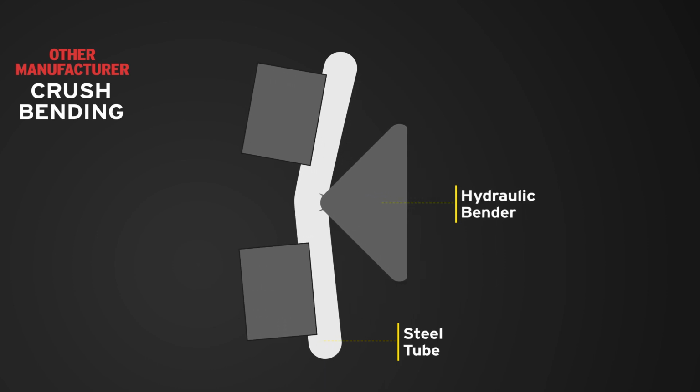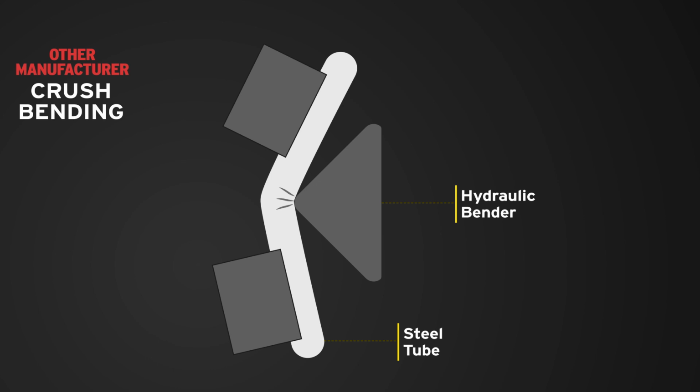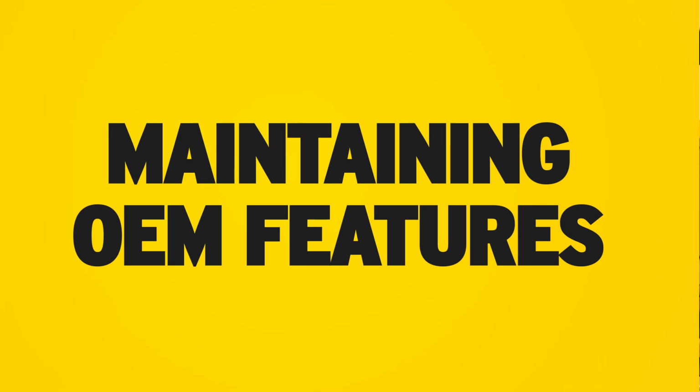There are a few types of crush bends, including wrinkle bends or standard crush bend. In both cases, the tubing diameter is reduced through the bend and overall flow capacity is compromised. Due to the consistent geometry and smooth surfaces of a mandrel bend, you will find that the factory converters found on most modern vehicles utilize mandrel bent tubing.